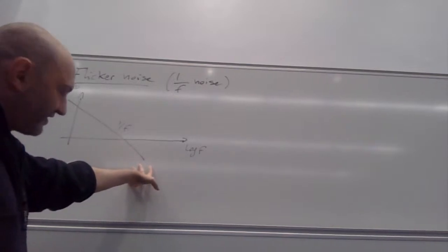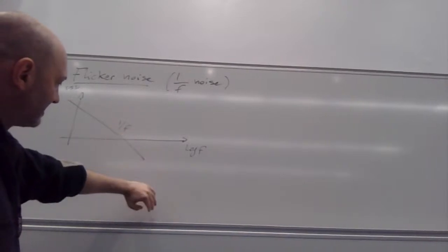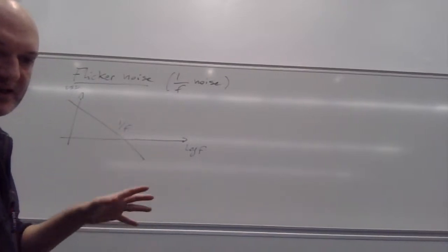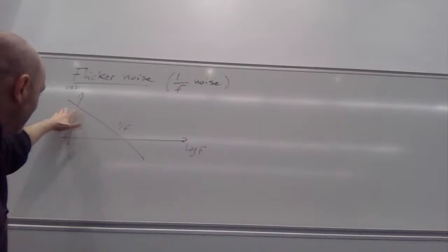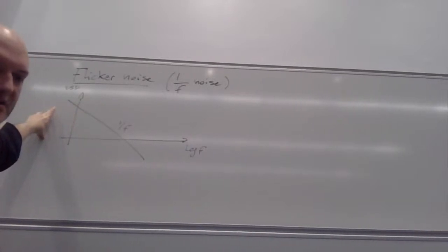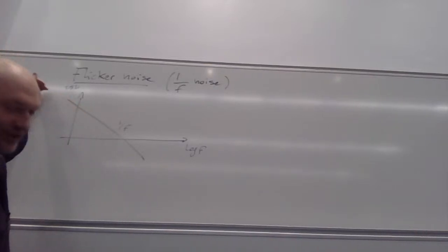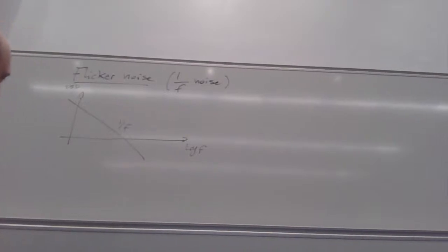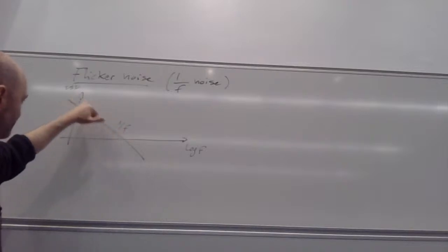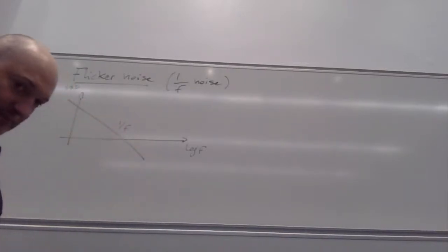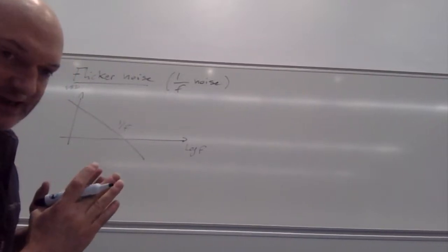Now, for higher frequency, we don't really have to worry because, like the white noise, there is a drop. Average around a few hertz. What you need to be concerned though is for the low frequency, because this noise does not converge and has never been observed to have a different shape. Okay. Now, in practice, that's not a huge problem because since you get power spectral density 1 over f, it means that you get the same amount of power in a frequency in a decade.